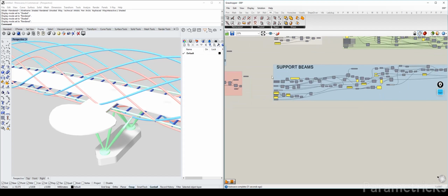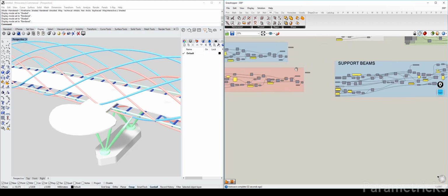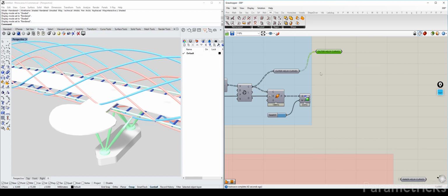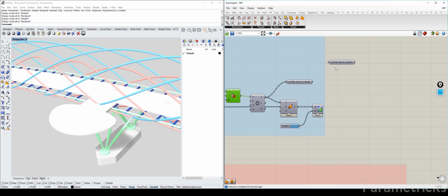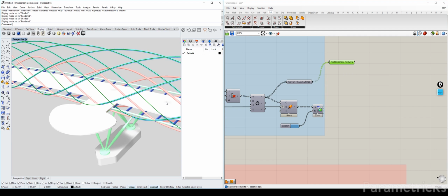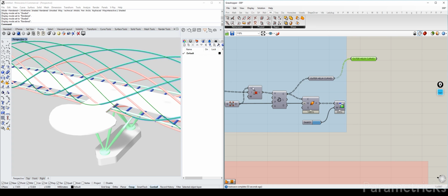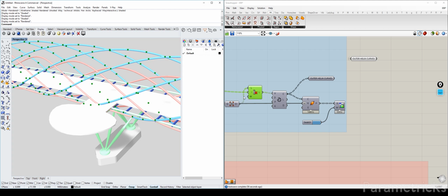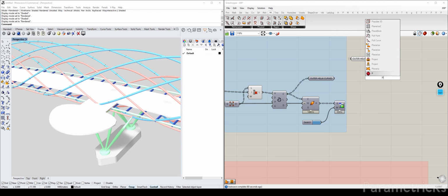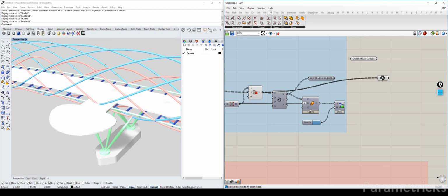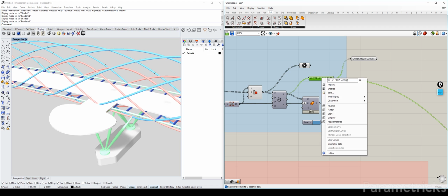Obviously, the next step is going to be needing the data from our outer helix or the major helix, whichever you want to call it. Not sure if you want the curve. I would prefer the points because intersecting a geometry with a curve can work, but ultimately what we want is the point data, because if we have the points, we can rebuild our curve. So let's go for the source. I'm going to make another component. Let's just call it point and do the same thing here, and then we can, what's this called?